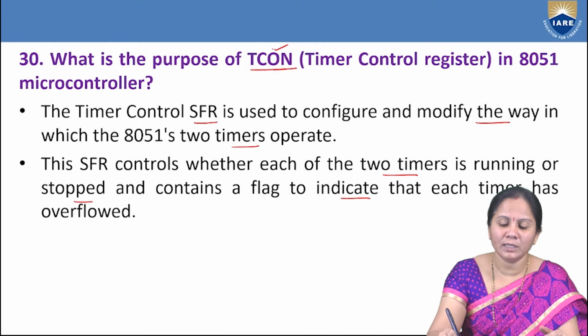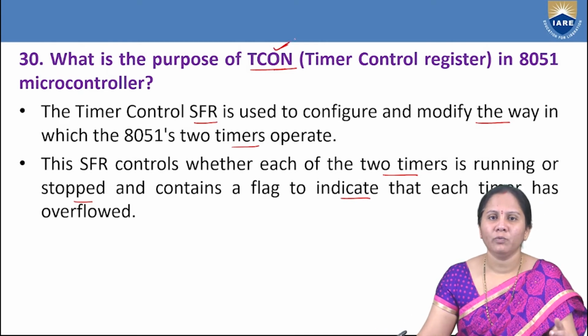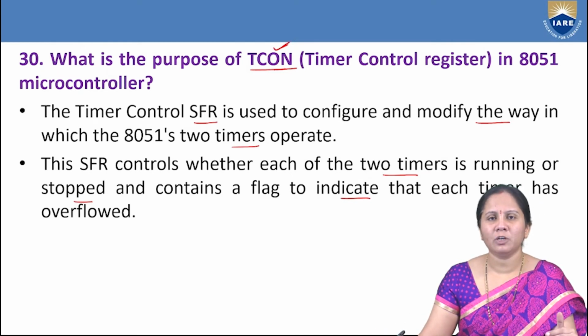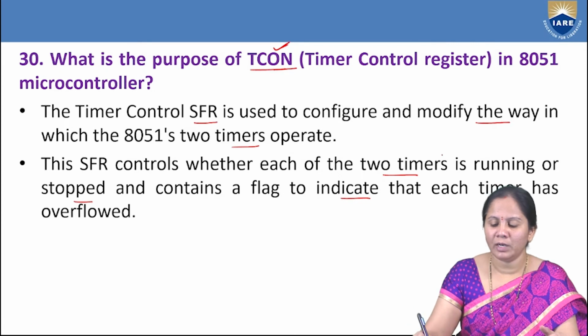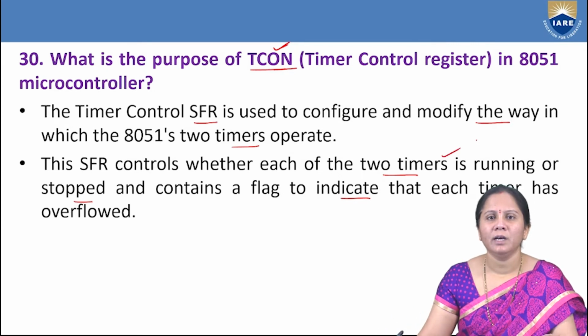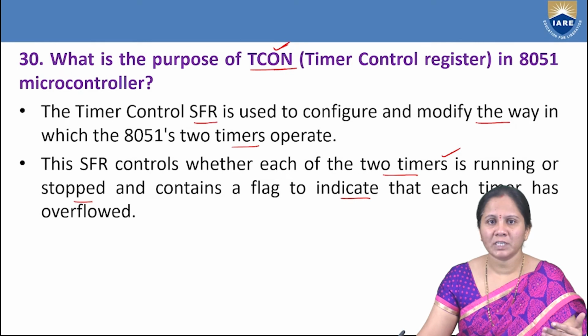If we see the TCON register format, all the bits present in that format tell us this information: whether a timer is running or stopped, or which timer has overflowed, because there are two timers.